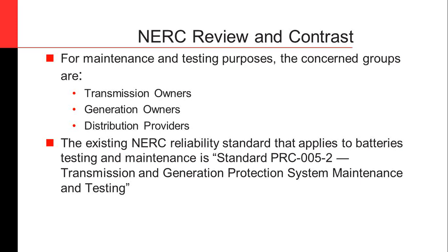It's actually based on what the manufacturer defines as a complete cycle. One manufacturer might say 80% is considered a full cycle, 80% depth of discharge. So in that instance, yes, 50% would not be half; it'd be about 60% of a cycle, give or take. Whereas if a manufacturer said 100% depth of discharge is considered a cycle, then yes, the 51% would be half of a cycle.